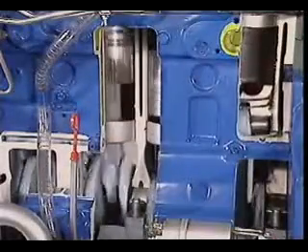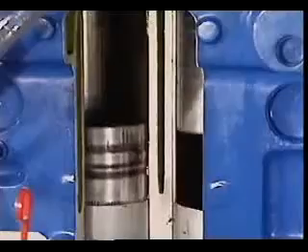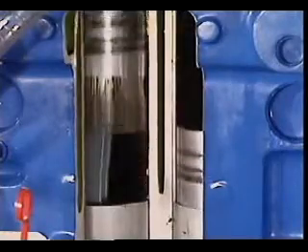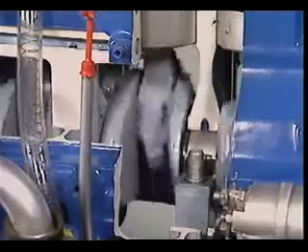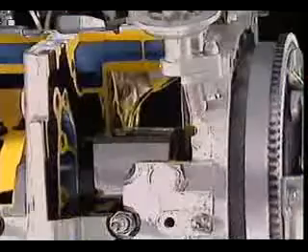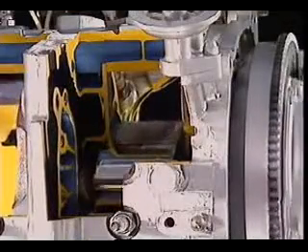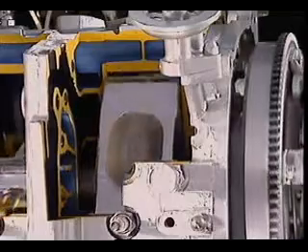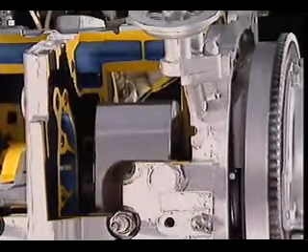A piston engine is called reciprocating because the pistons move back and forth over the same path. This reciprocating motion changes into rotary motion at the crankshaft. A rotary engine has a rotor, not a piston, and it's called rotary because the rotor has a planetary motion. It does not reciprocate.